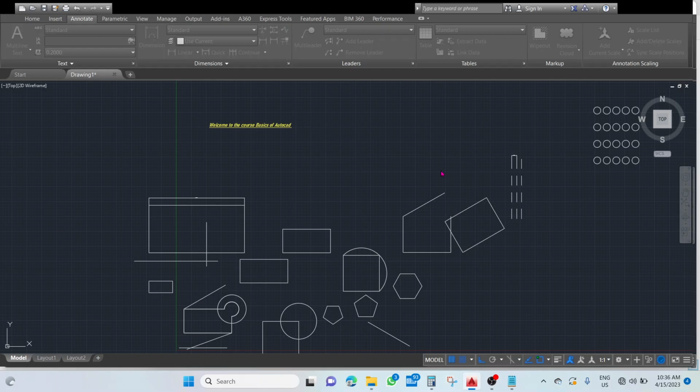Now in Modify, just make changes between these tabs. Go in Symbols and Arrows. Change the arrow size to 6, then text height, it is 2, make it 6, ISO standard, then primary unit 0.00, click OK, then press close. It is still not visible, so again go over there, modify it, change the arrow size to 10 and text height to 10, click close. Okay, somewhat it is visible.